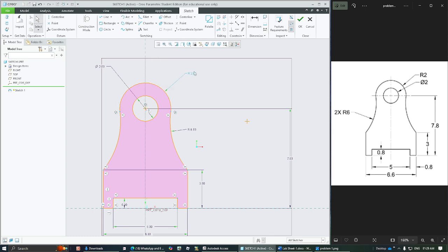option has appeared here. So Creo actually ensures that the diagram that you are drawing is completely constrained at all times. So whatever dimensions are required, it will create automatically. And in case you don't need any dimensions which are created by default, you just need to delete them, or you need to use the dimension command to create whatever dimensions you want in your diagram. And once you have defined all those dimensions, no other extra dimensions need to be left out. So this is how you will be able to create all the diagrams over here.